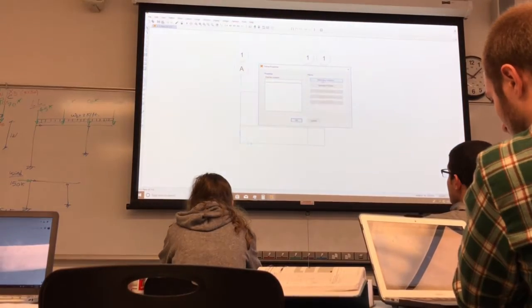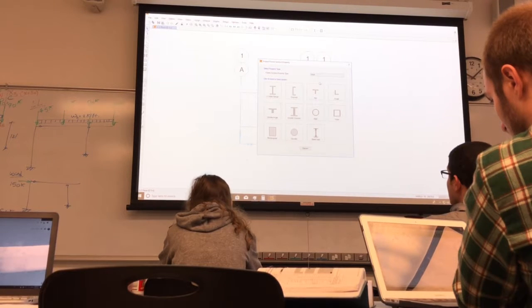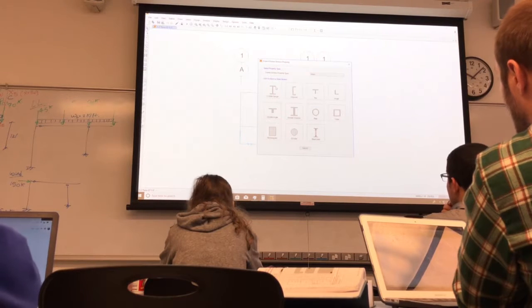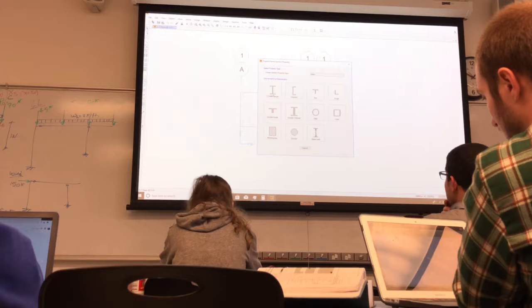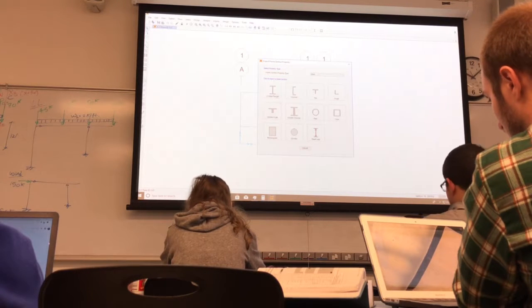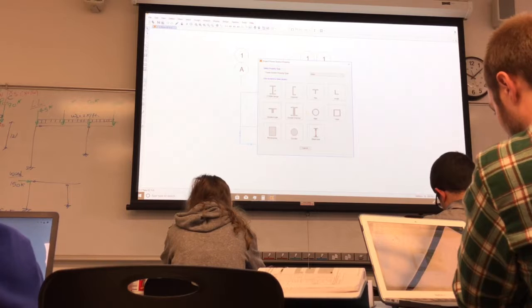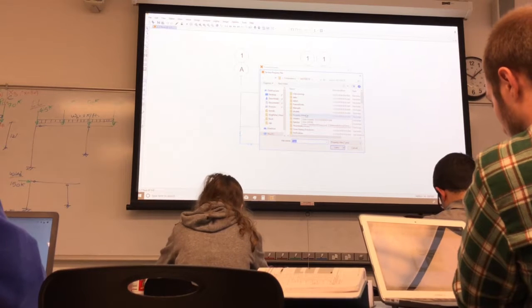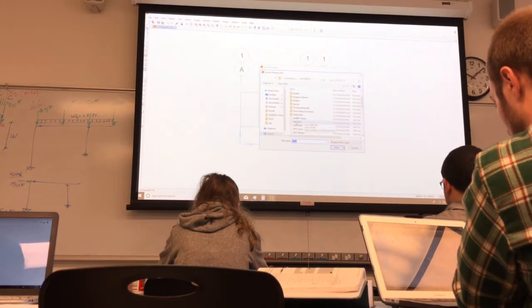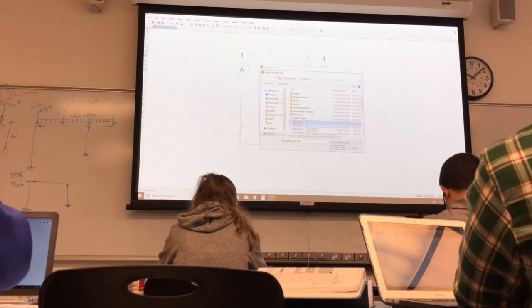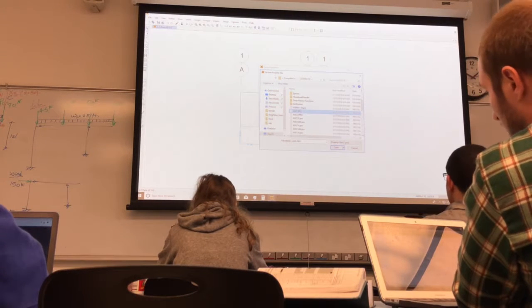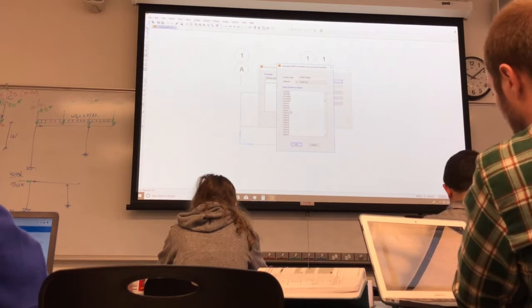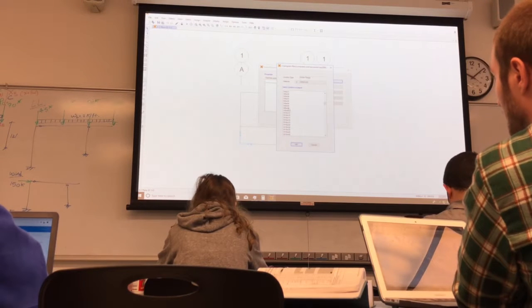I'm gonna go import. So if you click import a section property, it says here a steel section. So you have the option of concrete, aluminum, but we're interested in steel. So that's an I wide flange. That's what we need, a wide flange. A W section means a wide flange, I beam. Not interested in the rest. So click here. You see it opens a database where you can find all kinds of sections. So I use the AISC Pro database. It has all the sections. So if you scroll down, you'll find it here, and then you open. Find HP, you find M, S is the standard I-beam, and then you start finding the W sections here.